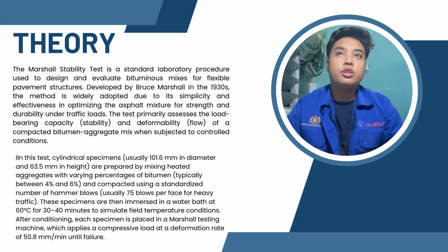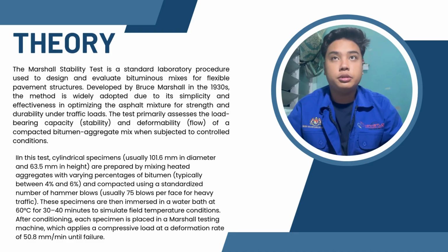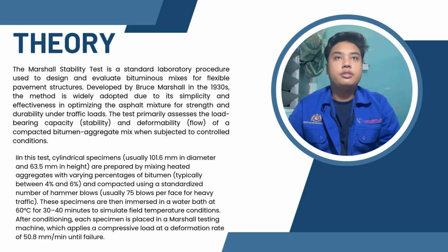17DKA24F1038. So for the theory, the Marshall stability test is a standard laboratory procedure used to design and evaluate bituminous mix for flexible pavement structure. Developed by Bruce Marshall in the 1930s, the method is widely adopted due to its simplicity and effectiveness in optimizing the asphalt mixture for strength and durability under traffic loads.